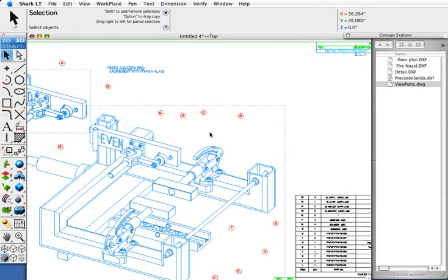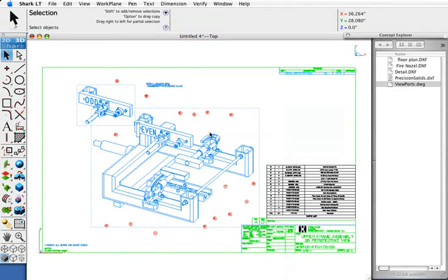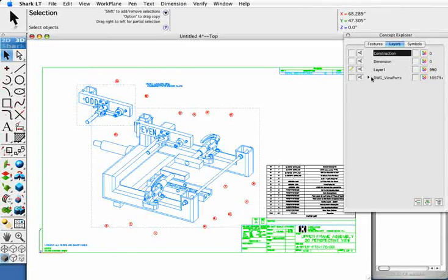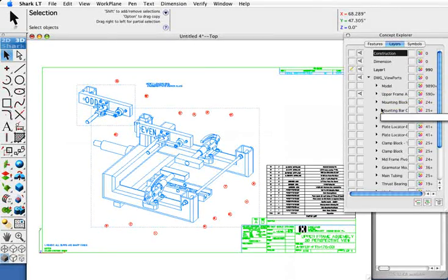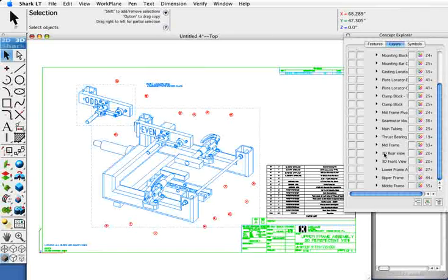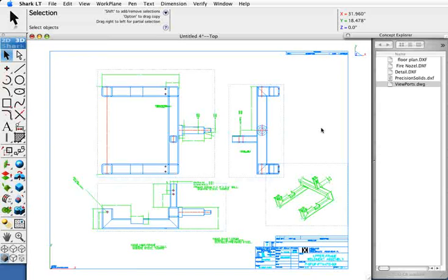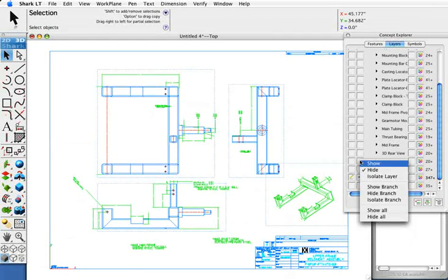Normally, the only geometry that you see is the title block, a border, and some annotations in paper space. Additionally, you'll see the viewports, which define regions and scales that go back into the geometry. When you read in a file with paper space, you'll see that the Layer Manager sorts the model geometry from the paper space or the sheets. To display a sheet or paper space, right-click, select Isolate Branch, and you'll see that sheet displayed. Let's display some more.